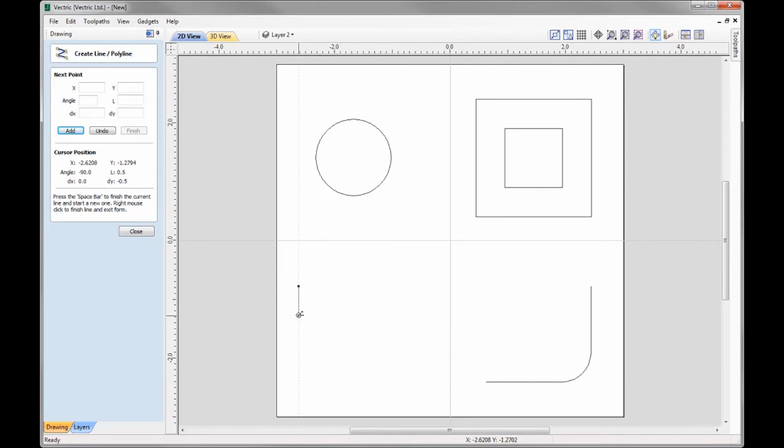Now when you create a shape, you can see here I'm presented with a vertical line. This just makes it really easy for me to create straight lines. And I can bring that down. You'll notice that I'm still picking up other points from the objects that we originally woke up. Okay, so I want to align that to the bottom of the shape, so I'm going to click here, and then I'm going to come across. You'll see now I've got a horizontal line. Again, really nice way for me to keep my cursor straight so I can create nice straight lines.